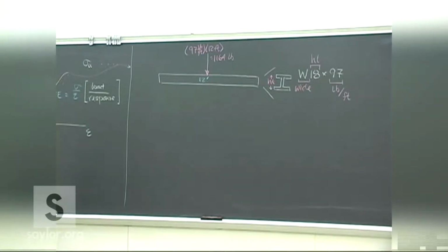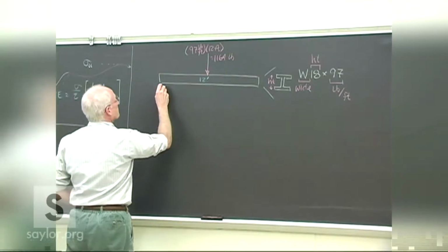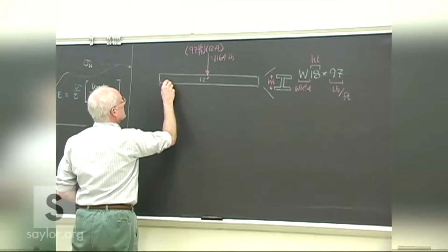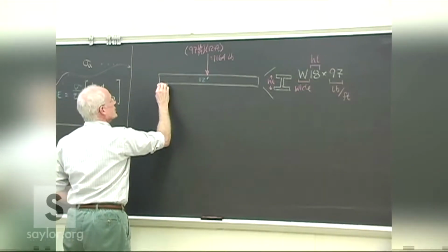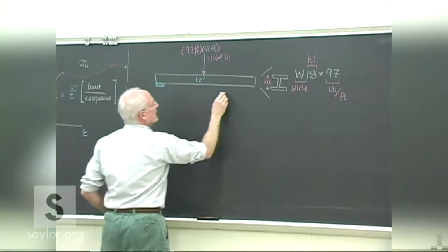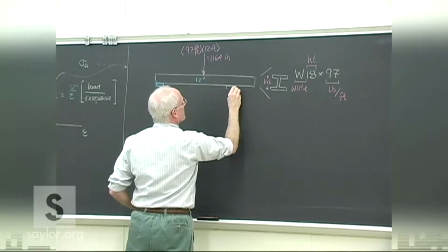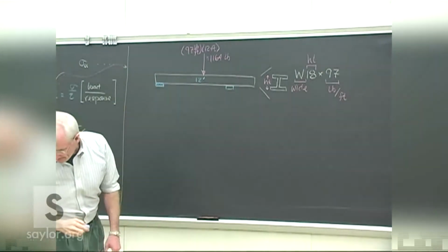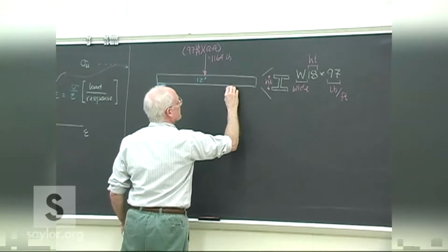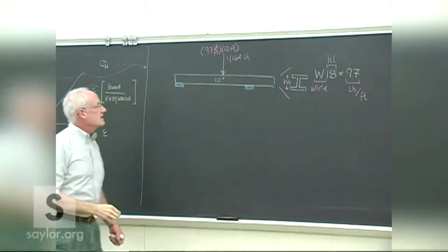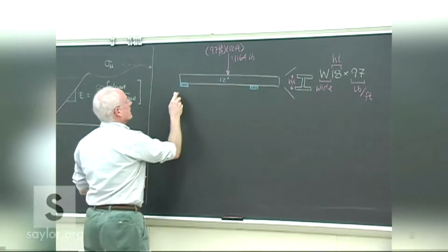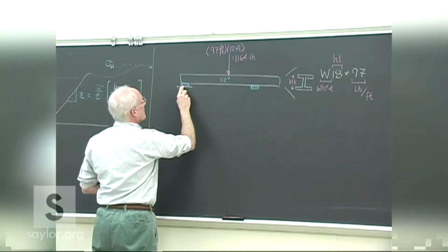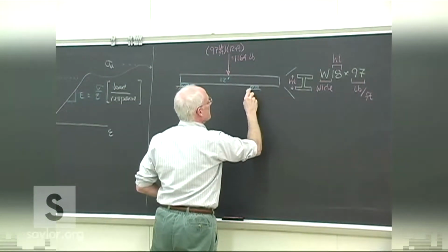Take that into account. Also, we're going to put some, imagine a small shear pad there and maybe about there. Yep, that's where I want to put them. And these we'll put about 8 feet apart. And that allows a couple things for this beam.